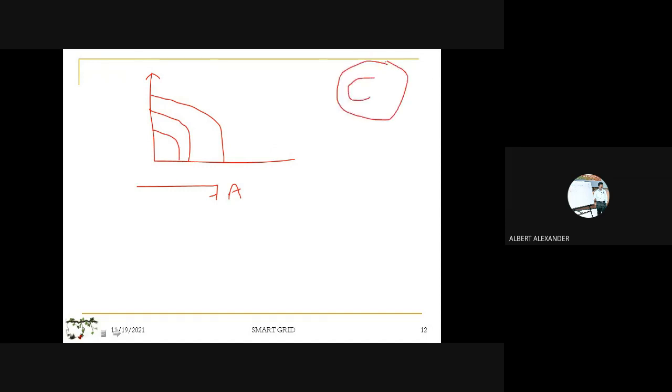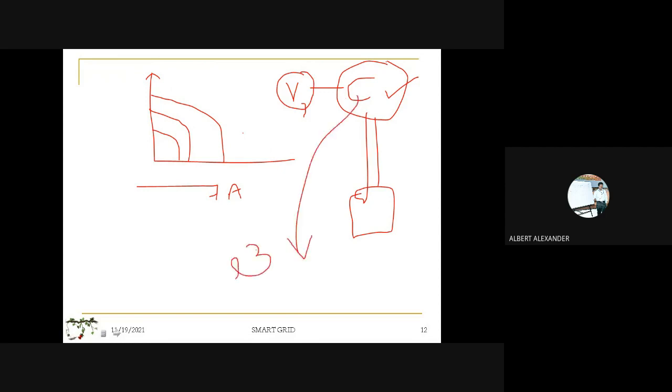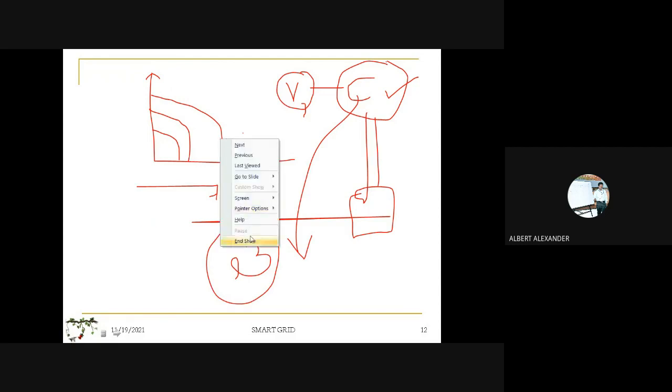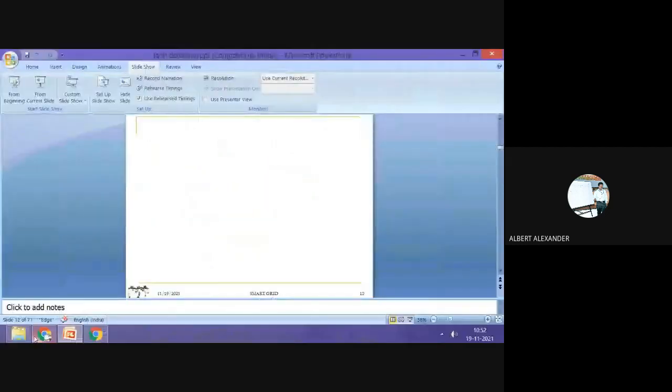The battery gets charged only when I'm giving the power supply from the solar PV panel connected to the battery. So I need to understand that by measuring the charging voltage alone, I should not take the decision. This charging cycle is classified into 3 stages. This is not only for the solar PV system, even for your mobile phones, so I will explain the typical cyclic difference in your mobile phones.